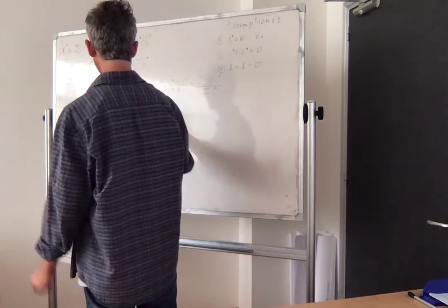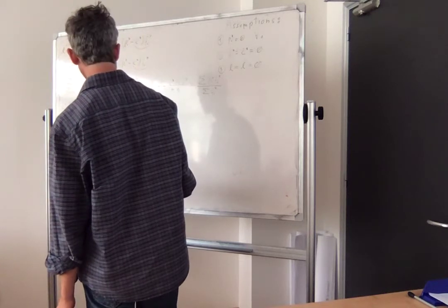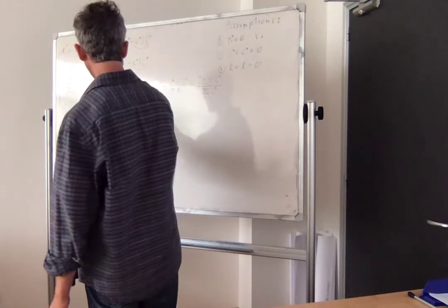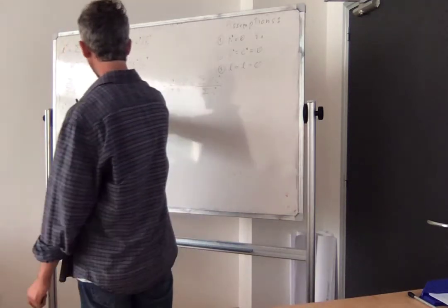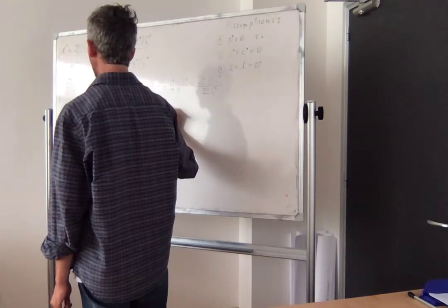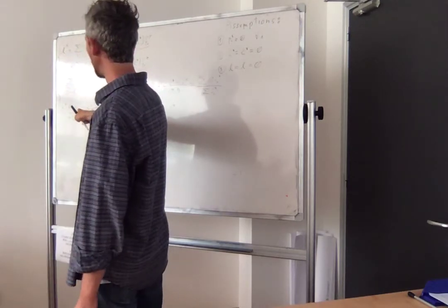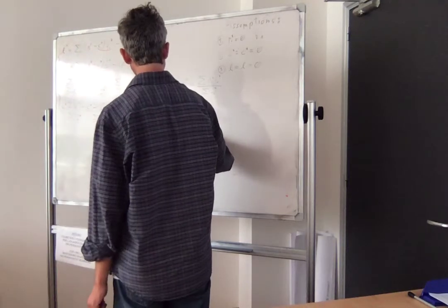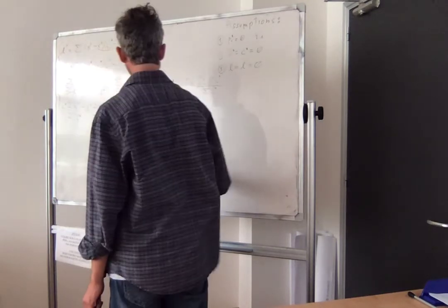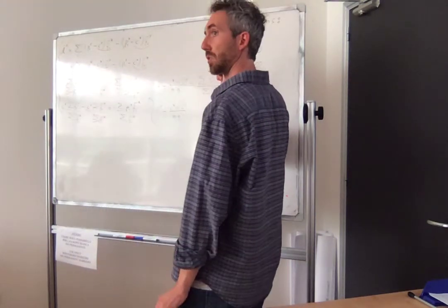And here, similarly, I multiply everything by minus 1 to make this positive. So I get Cx minus Cz. The summation of forces over x is m c double dot x. And the summation over z is mg, because I have no acceleration of the center of mass over z.